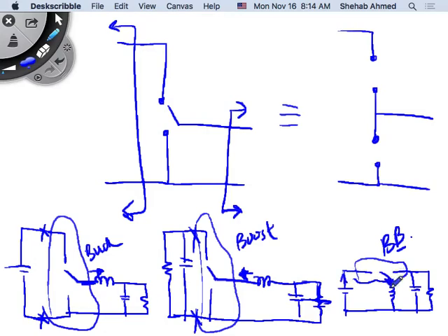Inductor current was in this direction, so current flows here and current flows this way. At the end of the day, these two terminals have stiff voltage sources across them, and an inductor in the output maintains current continuous for the switching period. They're all the same. All power topologies will be the same. Inverters will be the same. Everything will be the same.